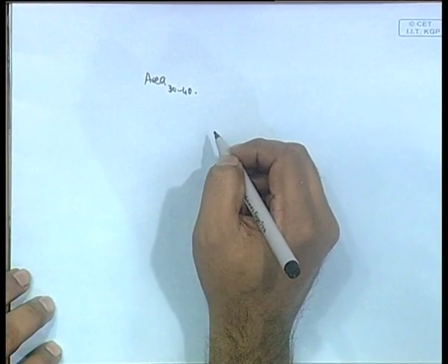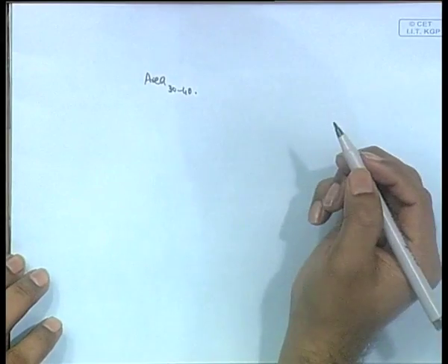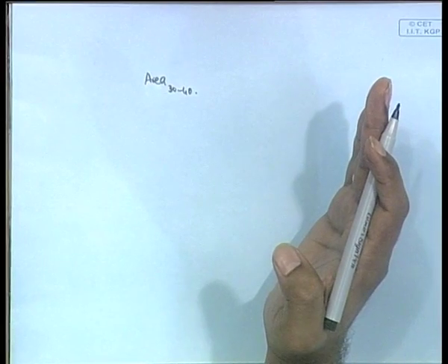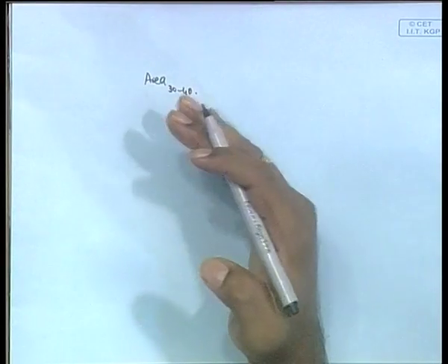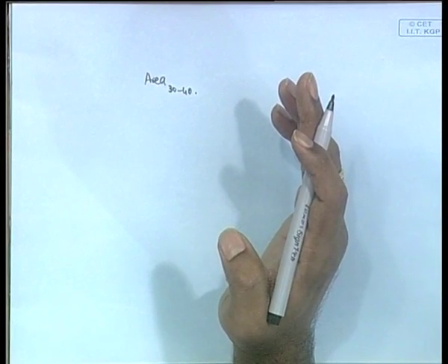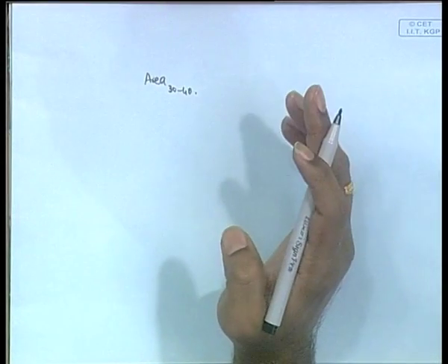Now, each of those you check, area up to 30 degrees you find, you see if it satisfies the regulations, in this case it does. Similarly, 40 it satisfies, between 30 and 40 it satisfies. So, three things you have to check. If all three are satisfied, then the ship is okay, all right.